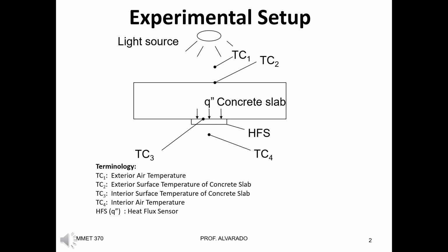And in doing so, we can capture the temperatures from TC1, TC2, TC3 and TC4. And we're also going to capture the heat flux passing through the concrete slab with the help of the heat flux sensor.